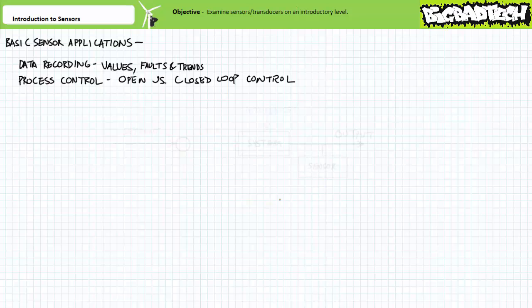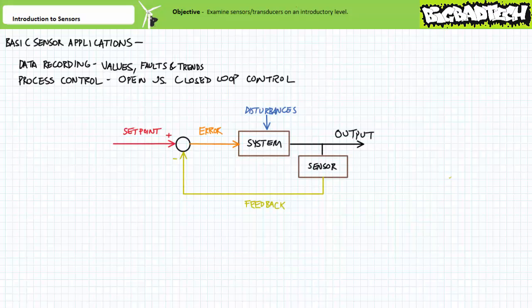Consequently, while simple and relatively inexpensive, an open loop control system cannot automatically correct any errors, nor can it compensate for disturbances. A closed loop controller, in contrast, is one that does use sensor feedback to determine if resultant output has achieved the desired goal. This means that the system not only acts upon, but also observes the resultant output of the process it is controlling. Consequently, a closed loop controller can compare the output process variable with the desired set point. If a differential between the output process variable and set point exists, an error in excess or detriment is registered, and the closed loop control system can automatically correct any errors and compensate for disturbances.